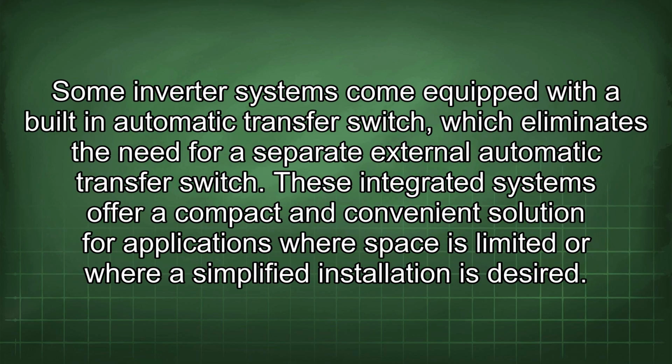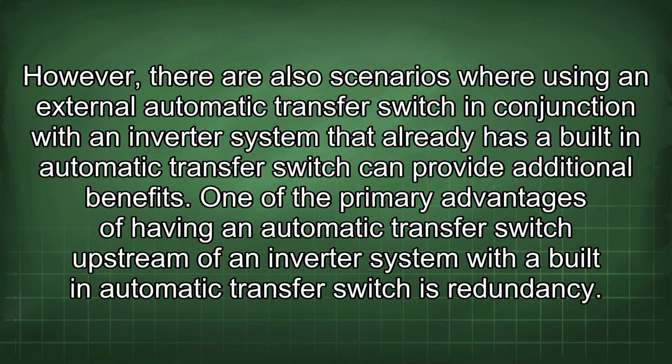Some inverter systems come equipped with a built-in automatic transfer switch, which eliminates the need for a separate external automatic transfer switch. These integrated systems offer a compact and convenient solution for applications where space is limited or where a simplified installation is desired. However, there are also scenarios where using an external automatic transfer switch in conjunction with an inverter system that already has a built-in automatic transfer switch can provide additional benefits.